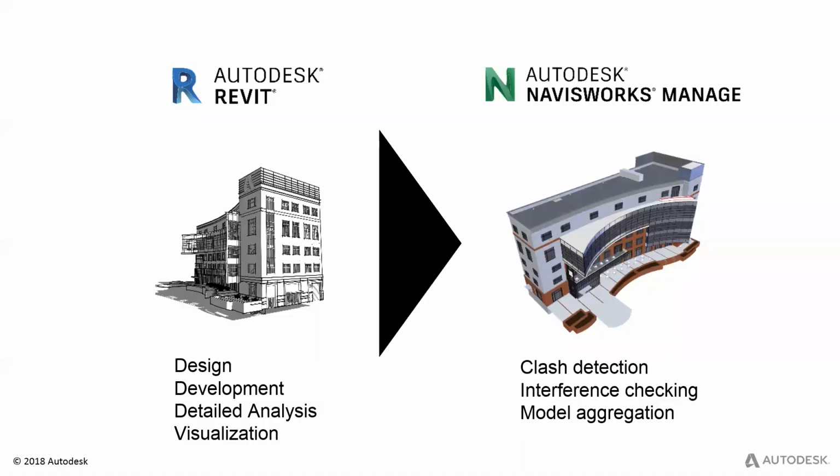So looking at moving along from your detailed design stage, looking at almost your pre-construction stage, or even at your construction stage, to be able to take your Revit model and push that into something like Navisworks Manage, and to be able to perform clash detection, interference checking, and to federate your models together. So Navisworks is primarily used for clash detection in my experience, and this is where you take a structural engineer's model and, for example, an architect's model, or you might take a mechanical engineer's model, and you do what's called a clash test.